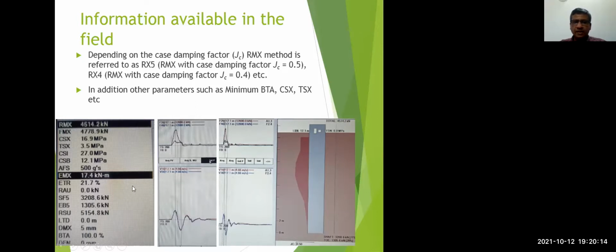So this is the screen seen by the operator, and you can see the acceleration here on this time acceleration graph, and the time velocity graph. And you can see one accelerometer is not working. In that case, it can be a problem with the fixing of the instrument, or else the blow is not perfectly applied. So you can actually disable that and then see, right? So these values will be based on that.